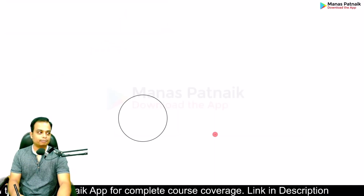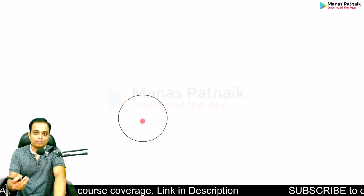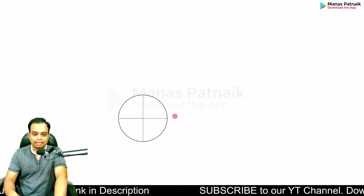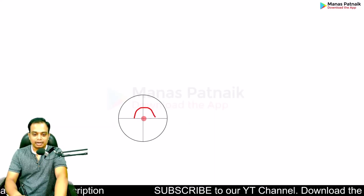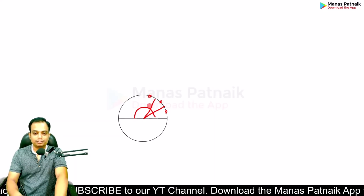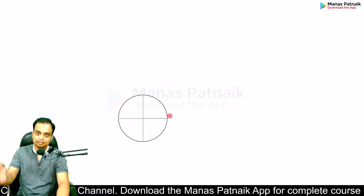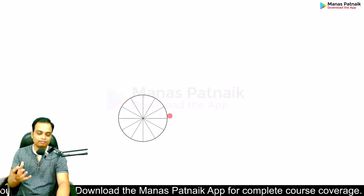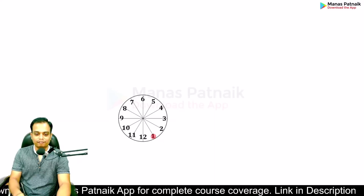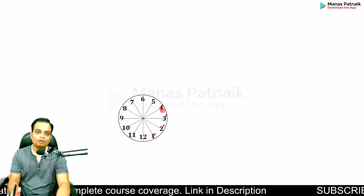Here we go. Let's start by first of all creating a circle. This circle is having a radius of 25, that is diameter as 50. First of all, divide the circle into 4 equal parts, and then you can keep your protractor over here, and then at an angle of 30 degrees, then at an angle of 60 degrees. You can see these are 3 equal divisions. The same process has to be repeated in all of these quarters, and when you do that, the entire circle is divided into 12 equal parts. You can number them from 1, 2, 3, 4. One more thing, when you do the construction, please number them as 1 dash, 2 dash, 3 dash, 4 dash. I forgot to do so.